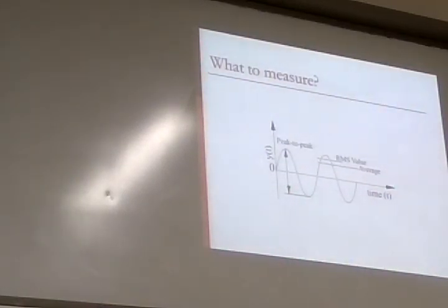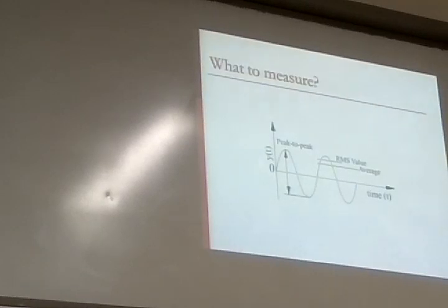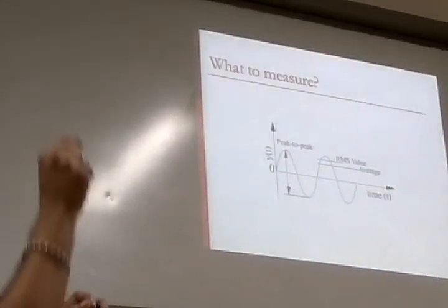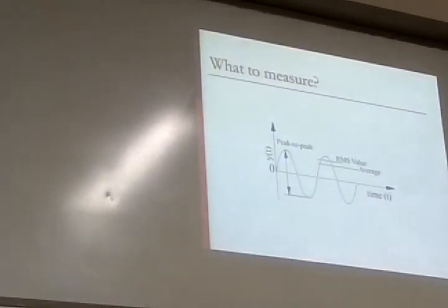Similarly, basically, if you take these vibration signals into a computer and then see, it's basically a time versus amplitude graph. So for every time instant, you will have an amplitude value. So it will be a column of values along with time. If you have a column of time stamps, for every time stamp you will have an amplitude value.